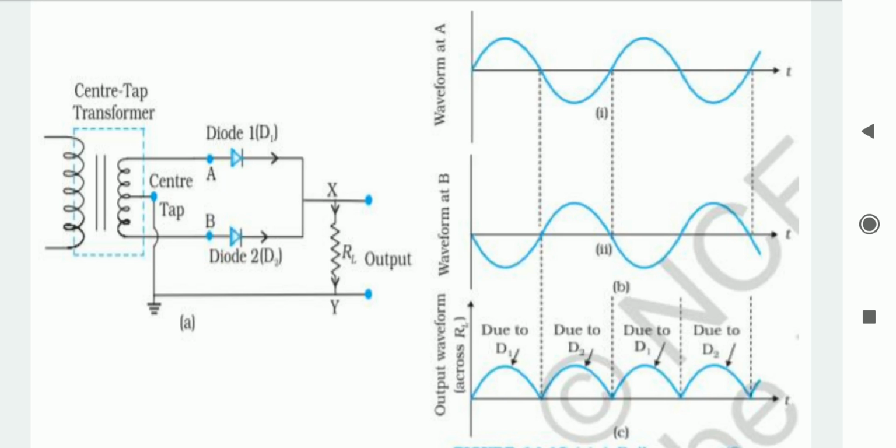But as you can see, from this rectifier we are not able to get any steady DC voltage; instead we get a pulsating DC response, and to filter out these ripples, these pulses, we use a capacitor parallel to the load resistance.